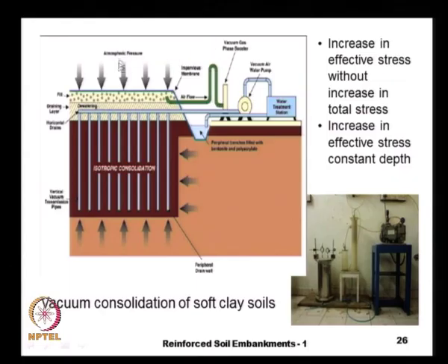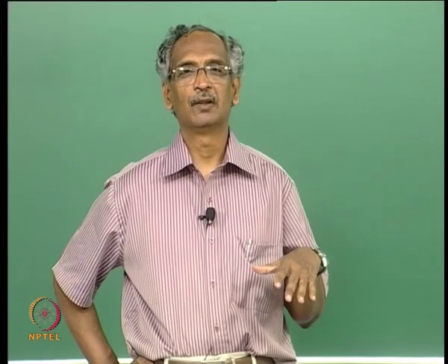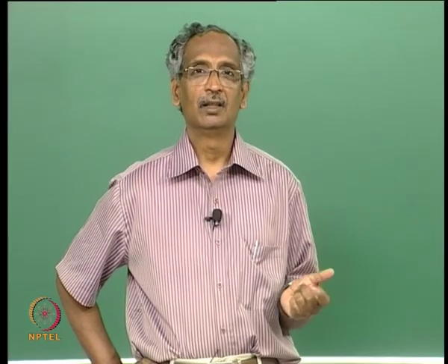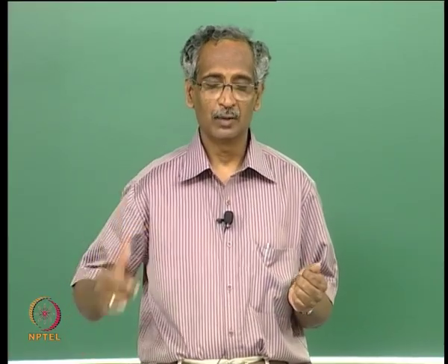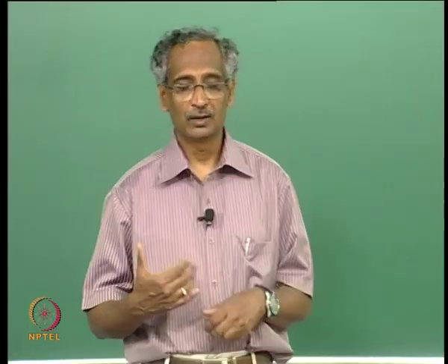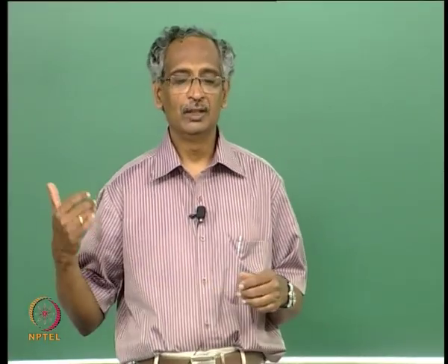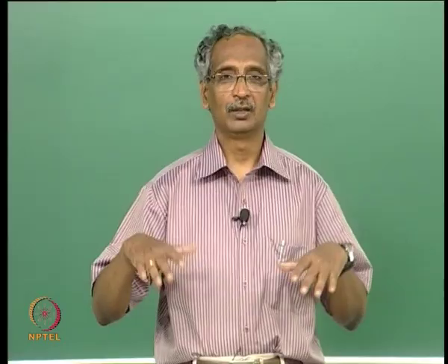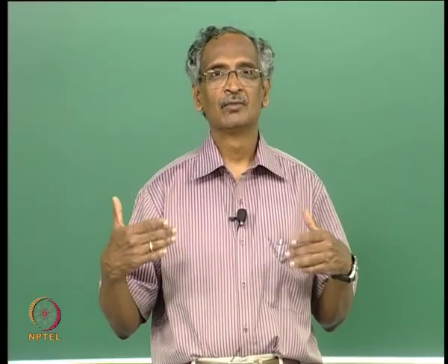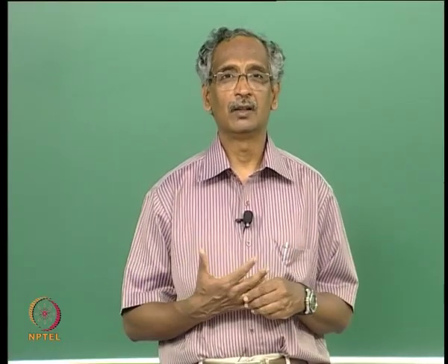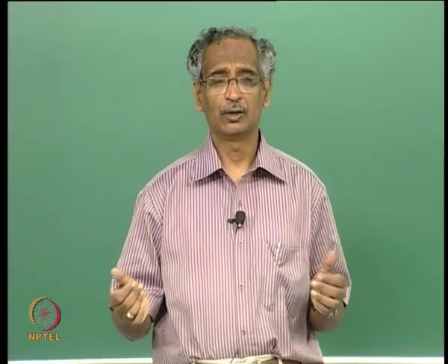That means that we do not need to bring in soil and dump it at the place to achieve the consolidation, and the increase in the effective stress is constant with the depth. That is the major difference between this method of treatment and the other methods, because in the conventional surcharge method we need to bring in the soil and put it in, and because of that the stresses that are generated are anisotropic.